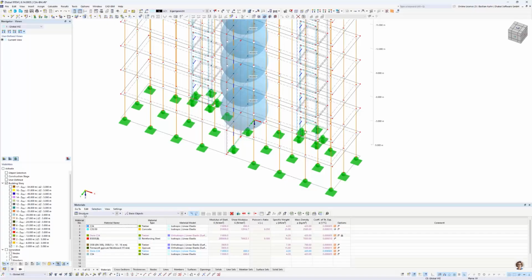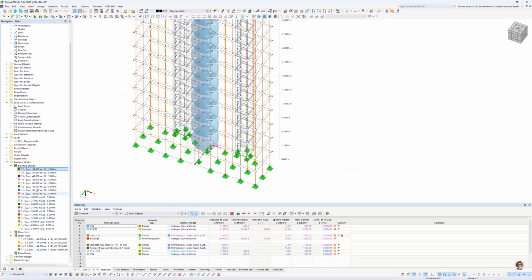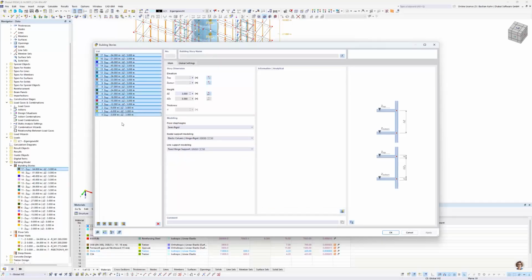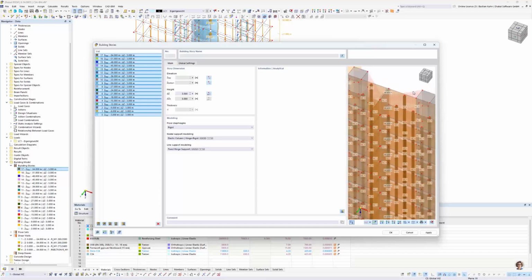All right. Okay, so this we could now calculate it with the semi-rigid stiffness again, but I don't think it's so much interest because I want to show you also the floor diaphragm rigid. And here the rest I leave all the same, but when we put on the rendering, you see that by defining the floor diaphragm rigid, you see this, well, little red dotted lines in here.